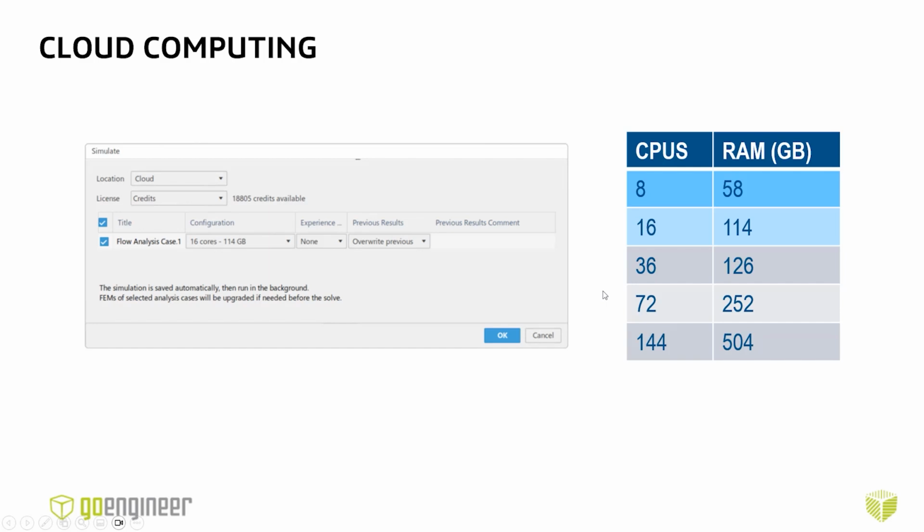If you think back to the comparison we did at the very beginning of this presentation, where I was comparing between my computer, my coworkers, and one of our better computers that we use for simulation services, I was increasing the CPU count. I went from 6 CPUs to 8 to 24. And as I went up, that improved the solve time. So that's the idea here. For something like this, which is just a ton of mesh cells requiring a ton of RAM, increasing the CPU count can also improve that solve time.